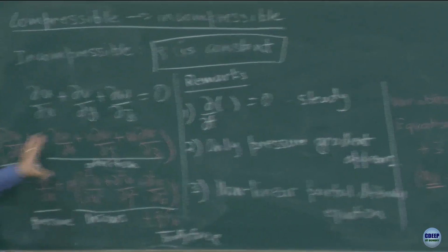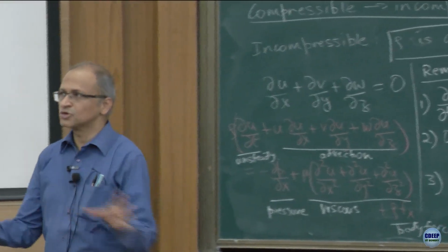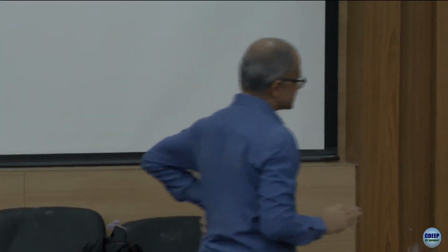Now, I'm not giving you the procedure for how to solve it, but if I have to solve it, how many boundary conditions are needed, how many integrations? Every time you look at it, think about how many times integration is happening. Every time there is an integration, I will generate a constant of integration, and I need to find the values of that constant from the boundary conditions. I know that at this point, along this line or surface, this is the value that the function or variable is taking. That's the boundary condition I'm using.